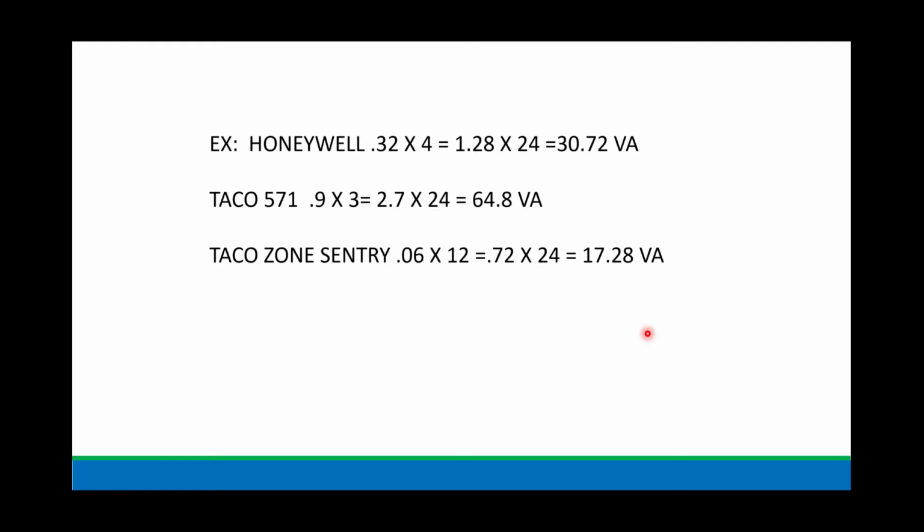And the way that valve operates, the body of it is a ball valve. There's no flapper, it's a ball valve. And in the motor, we have a circuit board. Since it's a ball valve, it's a quarter turn valve. So when there's a call, we energize the valve and open it, quarter turn, and then we cut power once it's open. On that circuit board, there is a capacitor, and the capacitor is storing power, so it's keeping the board energized.